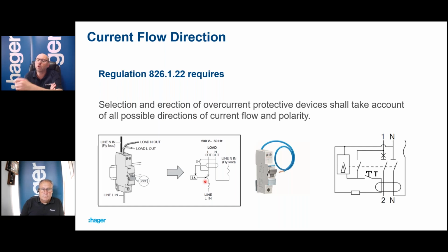So you'd be looking for a drawing similar to the one on the right there, wouldn't you, Paul? You would, yeah. So clearly you can see on the product, it might be described as single pole switch neutral in catalogs or information like that. Or we see these two contacts, one in the neutral. You can see clearly the difference there. On the neutral side here, there's no contact break, if you like, where there is on this product. So any product with this drawing on clearly would be a switched neutral type product.